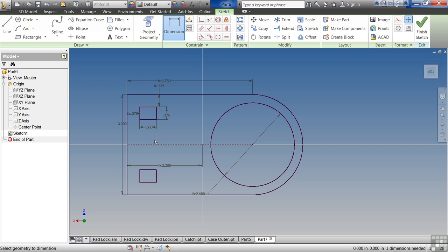Remember, capture it early, capture it as simple as possible, and you want to capture the constraints before you capture the dimensions. Basically, what shape should it be before what size should it be? And if you notice, the very last thing we do is the size. AutoCAD users, this is the opposite of what you're used to, and this is very hard for you to get used to. But sketch it out very roughly. Doesn't need to be pretty. It doesn't need to be nearly the right size.